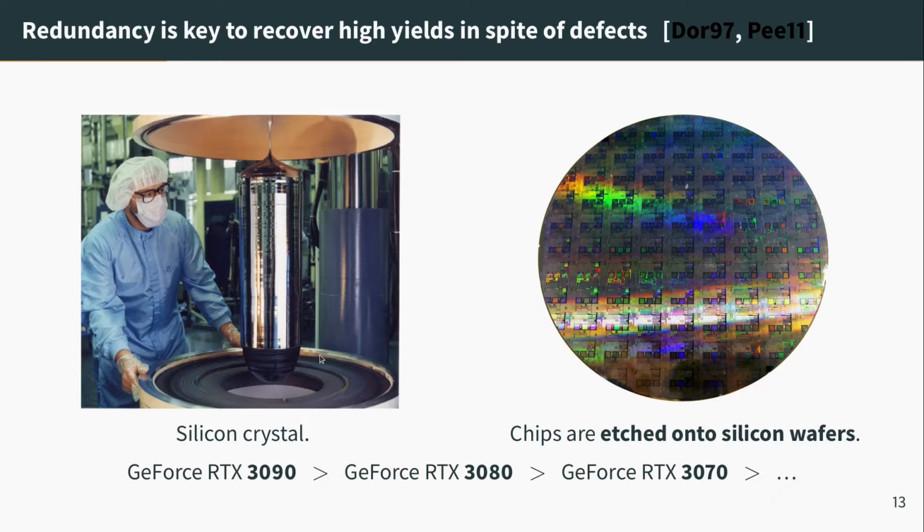So basically, you have a machine, with very specific physical conditions like temperature, pressure. You start from a core, and then it grows on itself. You wait for some time, and you end up with a pure silicon crystal. The typical diameter is like 30 centimeters or a bit more. And then you slice this into small disks, and then you place those disks in a machine that is going to etch